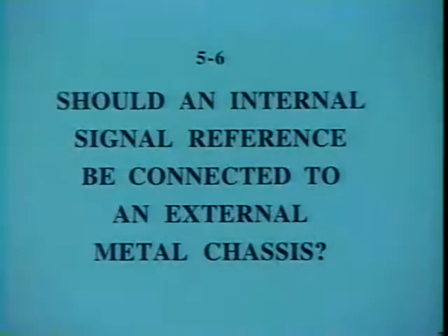Now, of course, the answer, as you might expect, is yeah, sometimes you want them connected and sometimes you don't want them connected. And what we've got to figure out is what are the situations that govern when we make the connection between the signal reference and the metal enclosure, and when do we not make the connection. Also, we need to figure out at what frequency do we make the connection. Do we make it at all frequencies, or do we only make it at high frequency and not at low frequency? Those will be the issues we have to concern ourselves with.